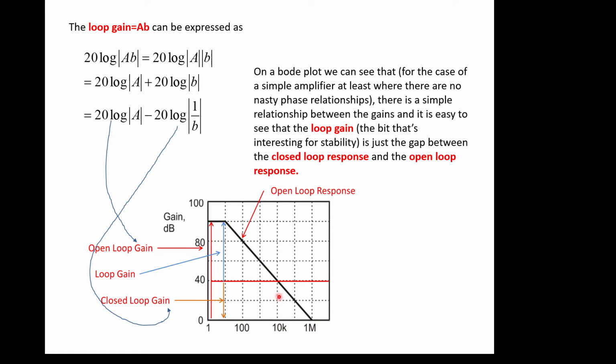So I've got a frequency response with a gain of 40 dBs up to 10k. And likewise, if I dropped it down to 20 dBs, I'd get a wider bandwidth response. And that's what we would normally look at for this.